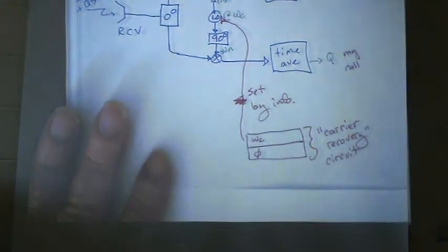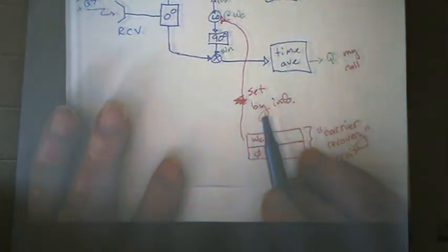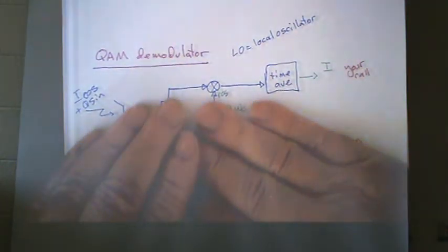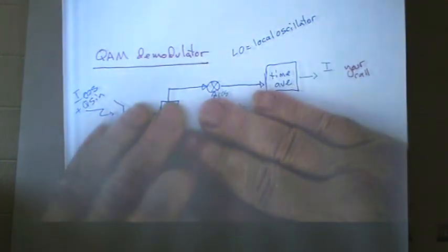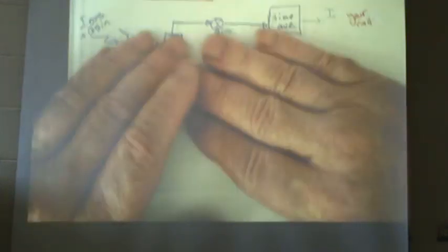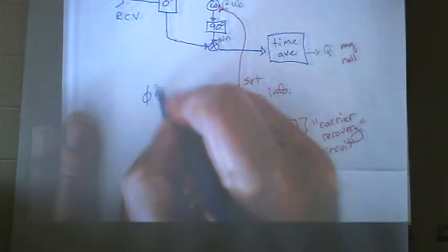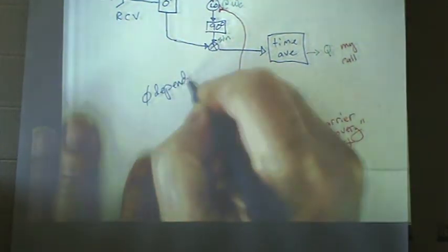Likewise, it has to work the same way in optical. That's why optical started in a more simple way. Optical started with just binary AM, and it doesn't care about the phase. Right? But we know we can beef up to higher data rates by going to these phase-dependent schemes, which means it's so-called coherent, as we said. Phase-dependent, we call this coherent.